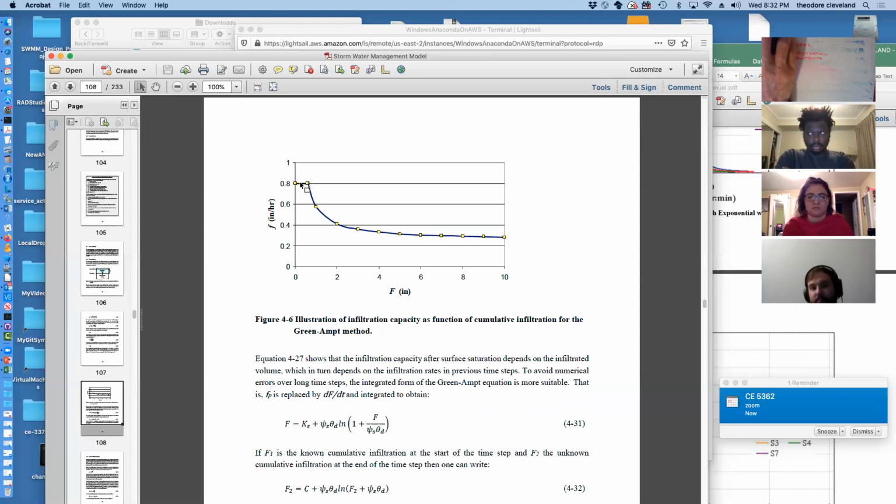We kind of have a high initial infiltration capacity, and then down here we have what appears to be an asymptotic rate. And I want you to quietly think to yourself, what's the difference between that curve and Horton's curve? And the answer that you may or may not conclude is there is no difference. It's a different set of jargon explaining pretty much the same phenomenological process.